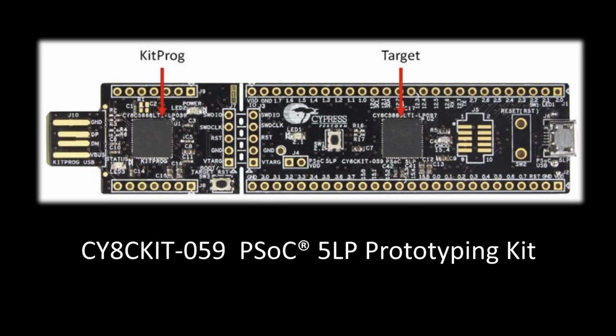This is what this device looks like, and you'll see that there's really two parts to it. The idea is that you can snap it apart. There's the programming side of it on the left, basically plugs into a USB port and then allows you to program the PSoC to the right, which is the main board. And then it's got all of these different connection pins that you can solder in for general purpose I/O type of pins. And some of them have some special uses, but in general, you've got quite a few just I/O pins that you can use however you want.